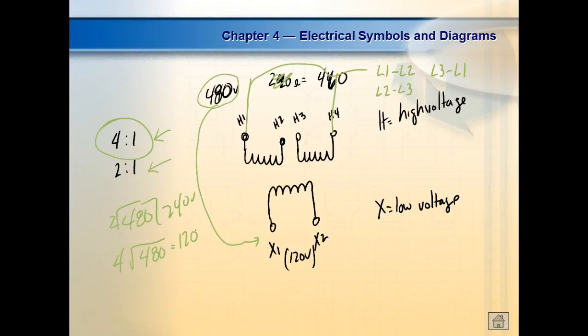So Jackson, how to wire that up to make it 120? We have to wire the primary up to give us 120. So how are we gonna connect those? Like H1 to X4, H4 to X2. If we take H1 to X1, we just blew up everything. Because we never, ever connect the H's to the X's, unless we run a ground, by the way.